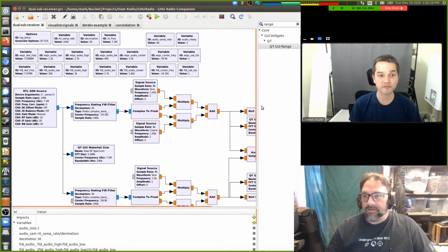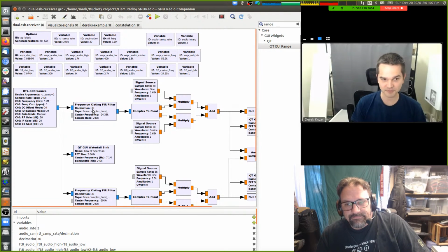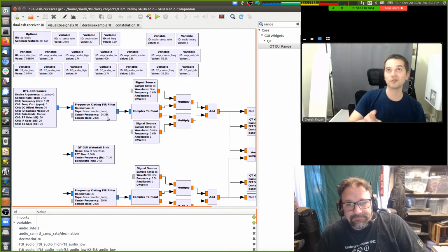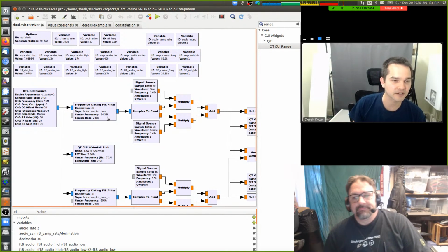So we're going to go through basically two operations here. One, we are going to do a frequency shift. And so in your frequency translating block, that's the first half of the name. Yep. You want to recenter your spectrum to the area that is at negative 24.35 kilohertz. And that is a relative frequency from your initial carrier of 7.1 megahertz, or your initial center frequency. Yes. Your initial local oscillator frequency. There we go. Yeah. Assuming this were a single stage heterodyne, direct conversion, basically.